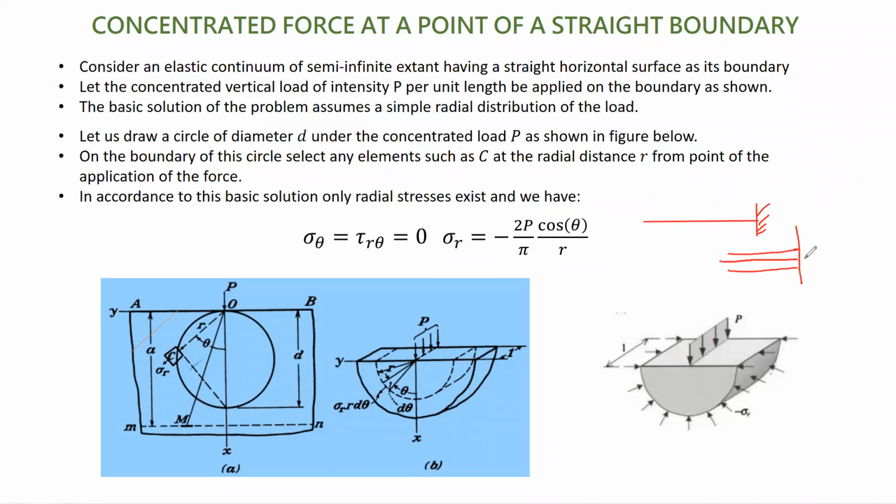So at the center line here, at this point, I say I cannot move vertically and I cannot move axially. So u should be equal to 0 and v should be equal to 0, for u in this direction and v in the other. So at that point, it is fixed. This point cannot move up, it cannot move down.